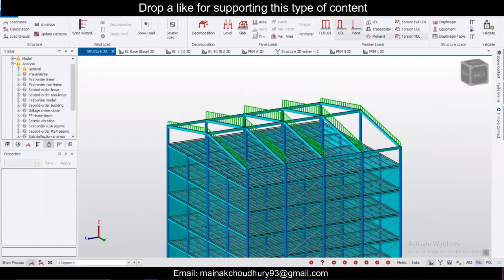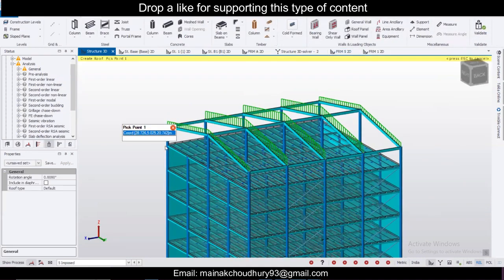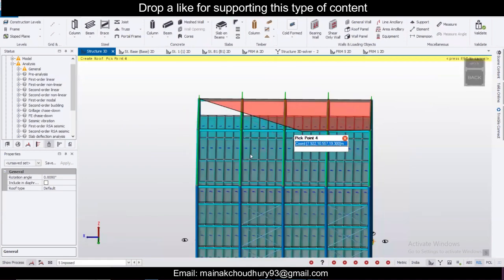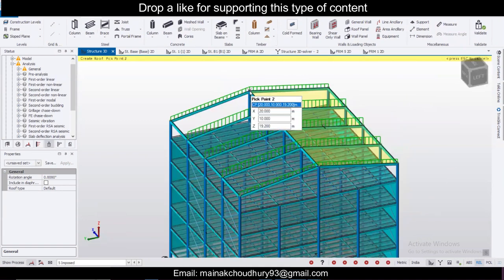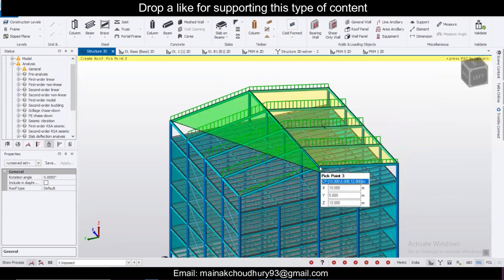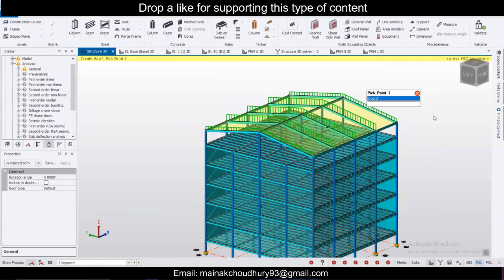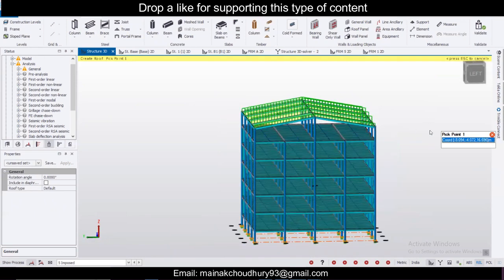Then I insert the roof panels. Okay, go to model, and you have the roof panel here. Okay, and then you can insert the roof panel 1, 2, 3, 4, 5. Roof panel 1, 2, 3. If I double click here, I think it will be done. Double click, yeah, done. You can double click or click at the end. So it's your choice how you can do it.